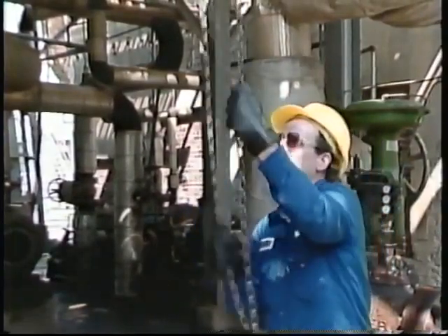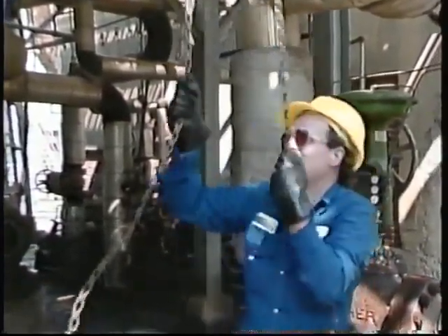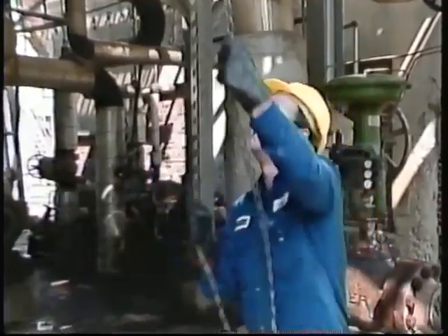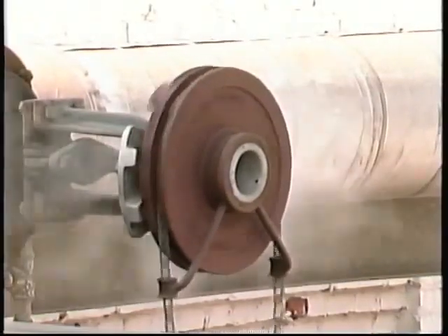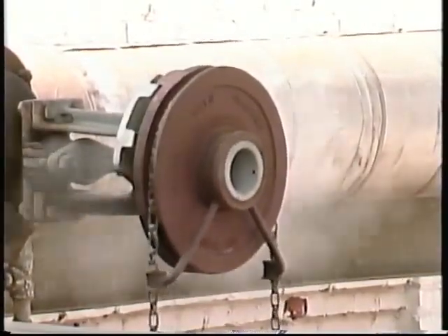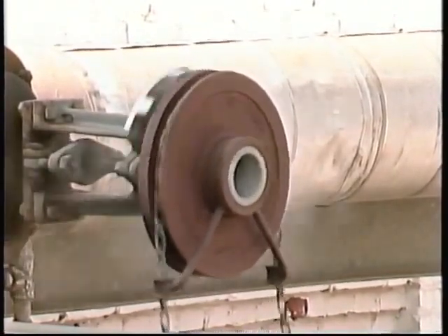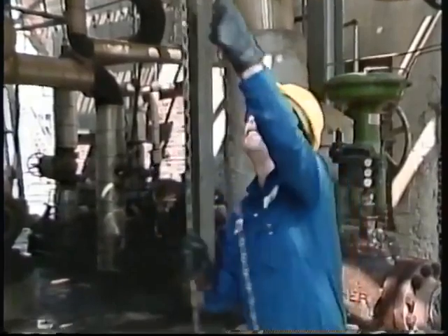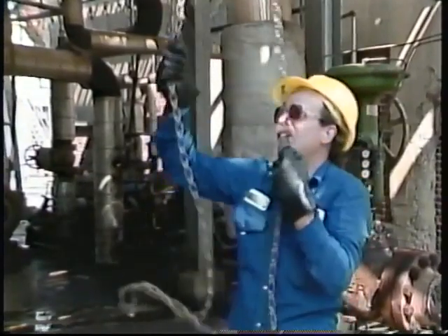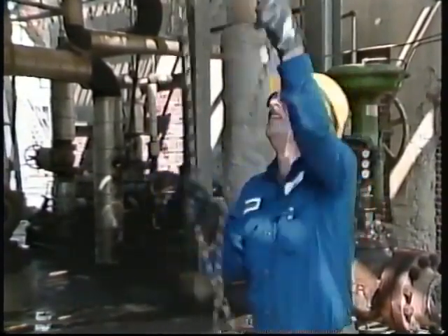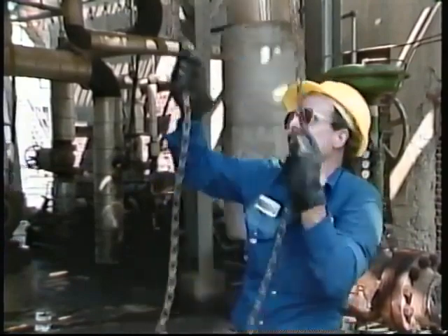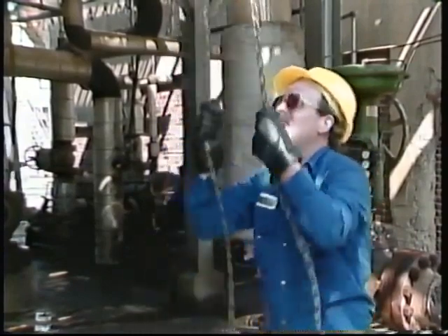The turbine shown here has only one exhaust block valve, located at the header. Cracking open the exhaust block valve allows exhaust steam from the low-pressure header to backfeed into the turbine. Doing that not only aids in removing condensate from the turbine and the exhaust steam line, but also allows the turbine to warm up slowly and minimizes thermal shock.